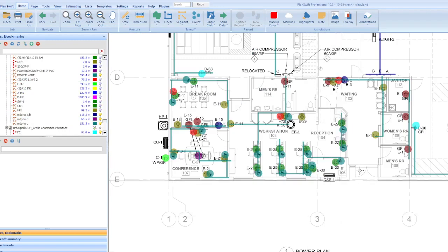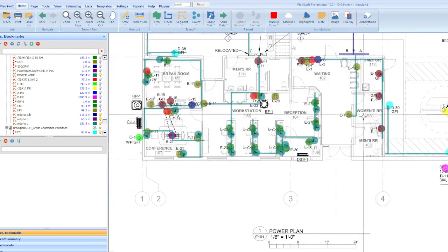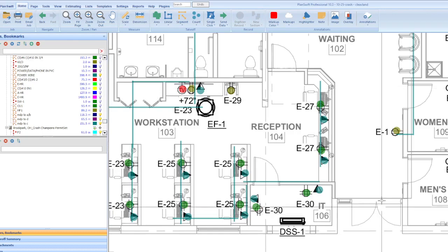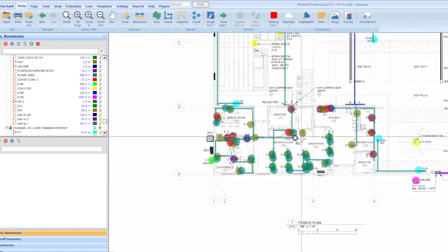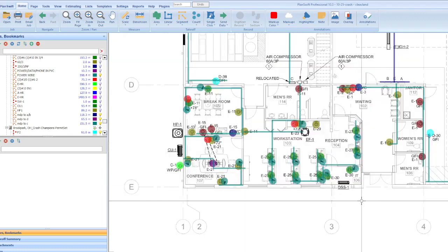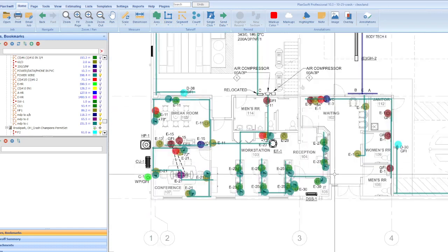See? So things I know that are going together to the same position on the panel. Okay, I'm going to run those all together, and then I'm going to home run that from that end somewhere to wherever here's relocated C, and where's E? So normally they'll put everything close. Yeah, here's E, panel A, E, and B, and C, and then the disconnects. Okay, so all we can do is make the lines from where the plans say the stuff is. Okay, and we're giving it a good representation.